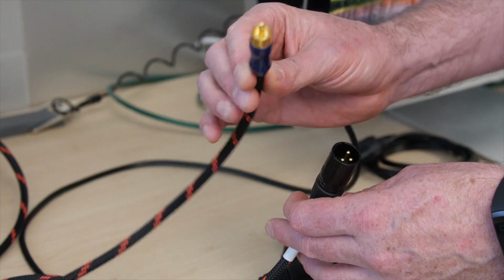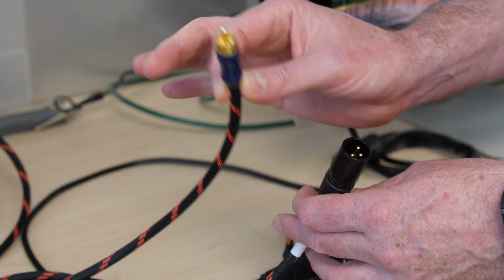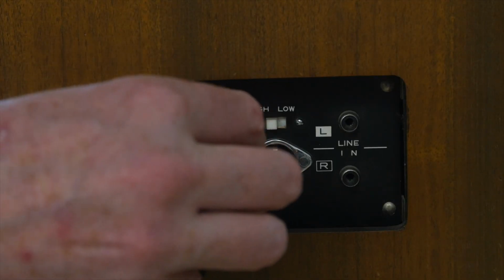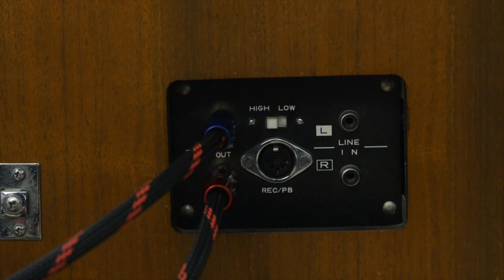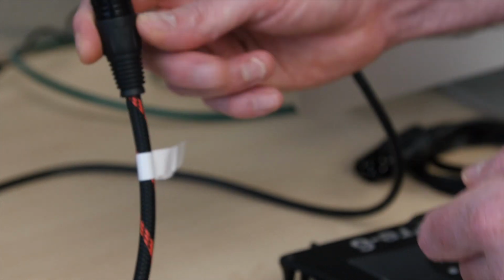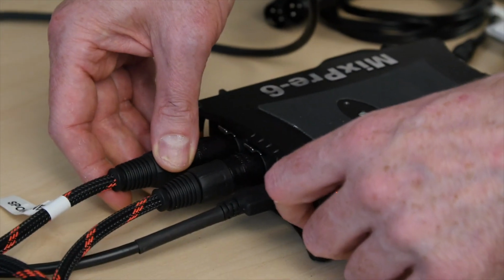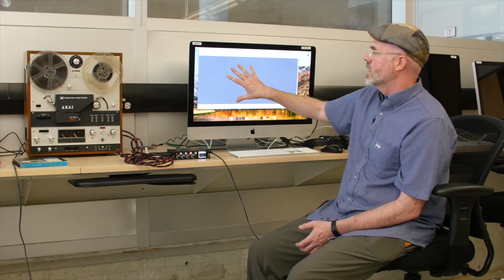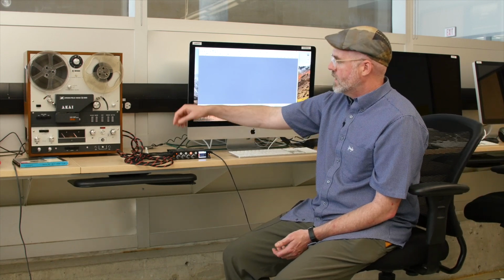And so we are using RCA cables to XLR, and it's male to male. RCA, and so you want to be coming out of here into our number 1 and number 2 inputs on our USB audio interface, which is what's going to be actually digitizing the analog and then bringing it into our digital audio workstation.